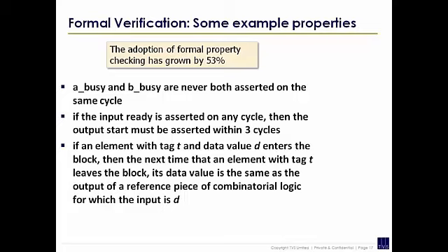So simulation is what we call depth first. If you ever remember computer science when you're talking about search algorithms, that's a depth first search algorithm. What formal does is on cycle 1, it will check every single possible state and look to see if these 2 signals are asserted or not. And then on cycle 2, it will look for every single possible state and see if they're mutually exclusive. And through the power of mathematics, there's a lot of proof engines to try and prove that actually on every single possible state, those are always going to be mutually exclusive. So formal is what we call breadth first.